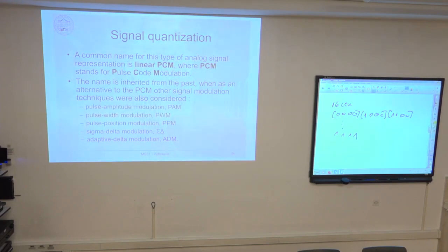So we have this high frequency binary sequence generated at the output of this sigma delta modulator, and this high frequency binary sequence is the input to the digital filter that computes the 16-bit value encoded by this high frequency binary sequence created by this sigma delta modulator. Okay.